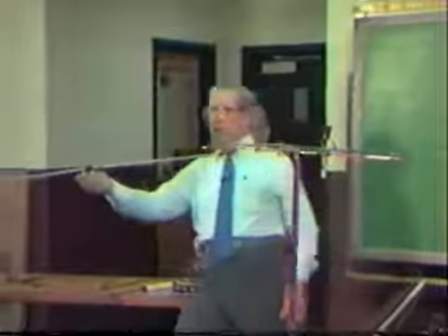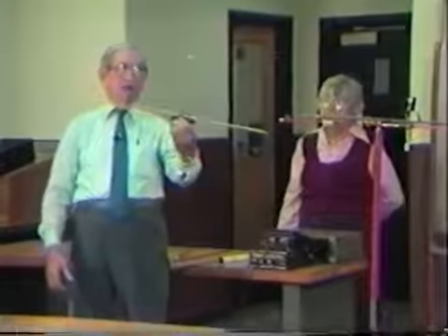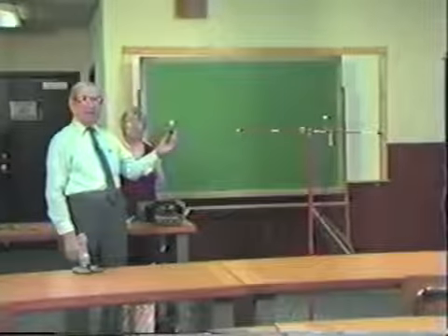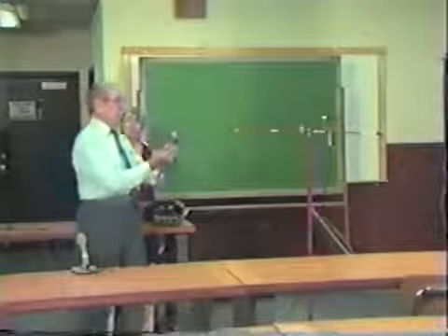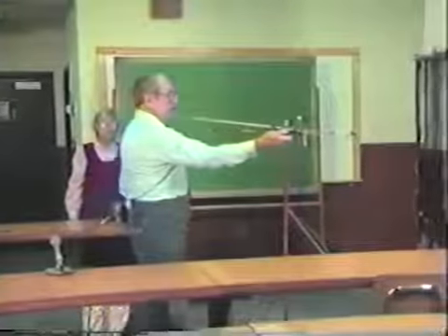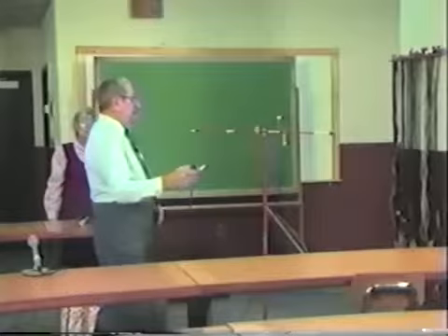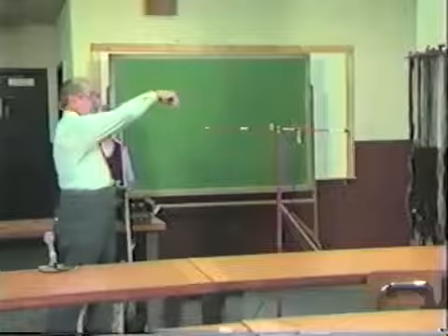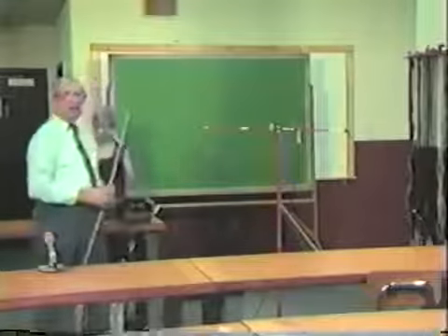Now, the same effect will take place when I use this antenna in a pickup mode, because when I turn this around in a plane opposing the receiving antenna, the signal falls off. If you remember, when I brought this antenna over to the side, there is no pickup. So the dipole antenna is broadcasting with two tremendous lobes on either side. And I hope that's clear to you.